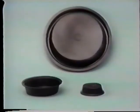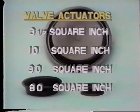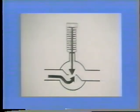The size of an actuator is referred to as the diaphragm area and is stated in square inches. Robert Shaw valve actuators come in 4 sizes: 3.5 square inch, 10 square inch, 30 square inch, or 80 square inch of surface area. The size of the actuator provides the ability to close the valve against system pressure or to open it within the acceptable limits of the valve ratings.